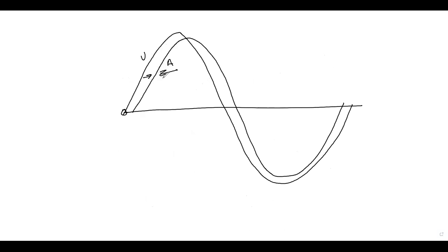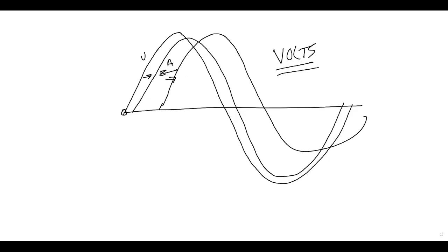This volts line is going to move up and try to get right in phase with amps. If I put too much capacitance on the line, it'll actually put the volts line way out here. Now my line has too much capacitance. But every time a capacitor bank operates, opens and closes, it is moving the volts line. That is it, and that is all. It is trying to bring the volts in phase with amps, right? That's the thing I can control on my system.